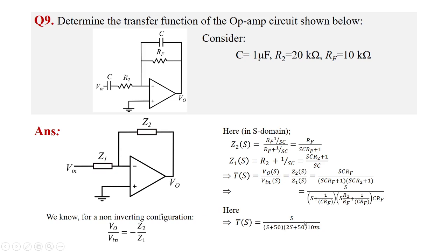So in the next question it is just to find the stability. Finding stability is just to find where the poles lie. Here the pole is at minus 50 and at minus 25. Right. So these two lie on the left hand side. So the circuit is actually stable.